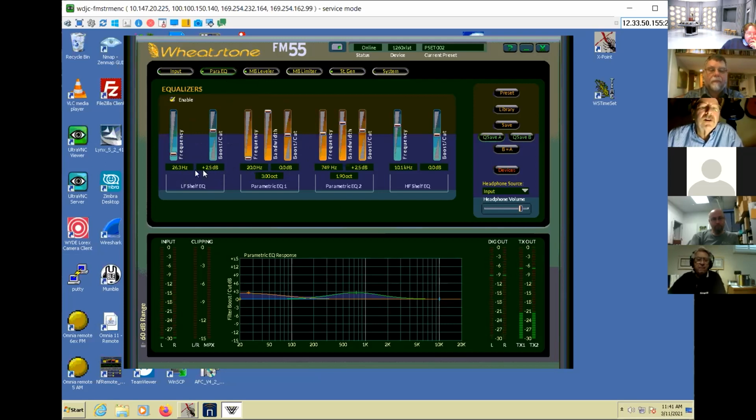All right, we're going to start talking about how we'd like to adjust this. Frankly, I think that's a little too low, but I'm using one of their presets, so I'm not going to touch it. We're boosting by about 2.5 dB on the bass. We're flat in the 200 hertz, which I call mid-bass, low mid-range. 749, which is right square in the mid-range. We've got a little bump on it. Now, that might strike you as odd. You know, why do I want to bump the mid-range? Because isn't that going to make it sound honky or boxy?